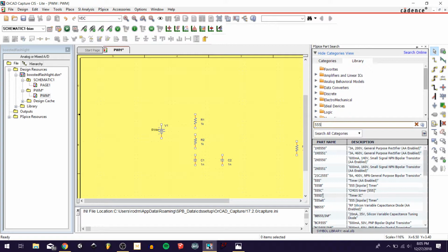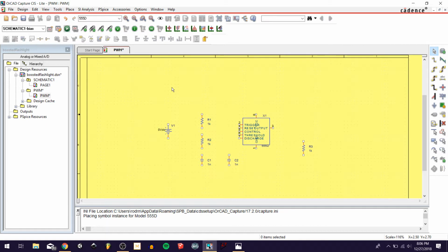So just come down so your mouse is on the 555D, double click that thing, or maybe single click it until you get the finger, and then double click to grab the component. Then come out here, drop it down with a left click, and hit escape to exit placing 555 timers. And I'm going to exit this to get a little more real estate back.